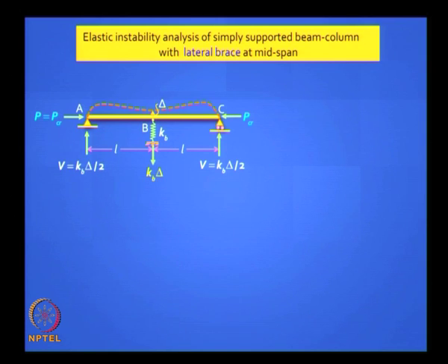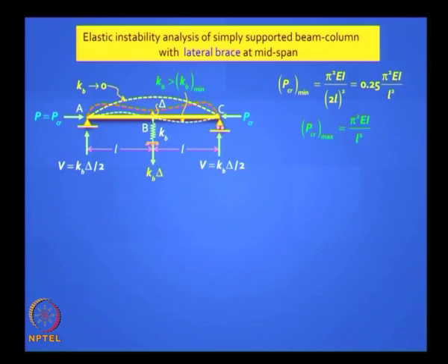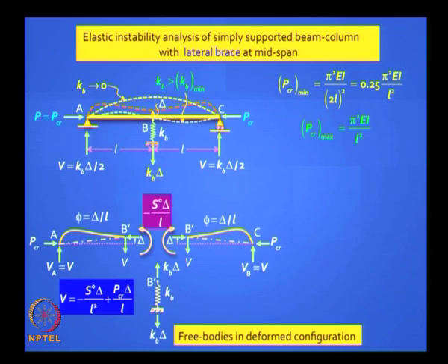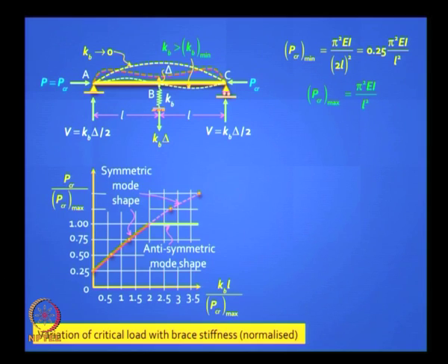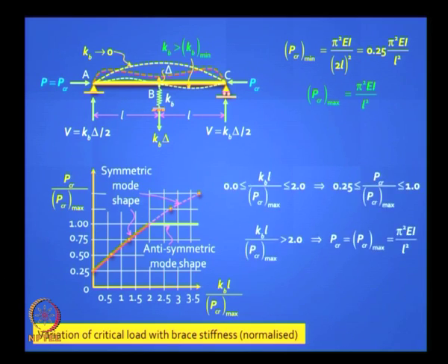Well, I can prove it from first principles by solving this equation. I can write my equilibrium equations, I write my stiffness values. You can do an equilibrium study of this, solve the equilibrium equation. Here you have moments coming into the picture which were not there when you had the hinge, and the moments are related to your stiffness measures. So plug in those values, solve the equation, it takes a little while, it's explained in the book. You will get an interesting result: you can find the critical value and it turns out to be exactly the same solution.